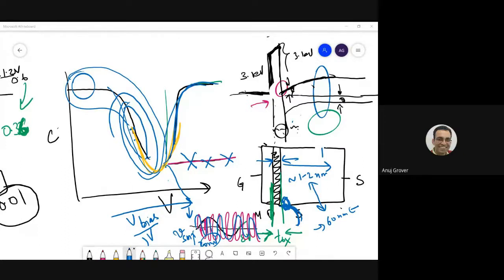Yes. I had mentioned once that we would use high K metal gate dielectrics and we could pin the VT to some level. I could modulate the VT of the device. What do you mean by modulating the VT? You will modulate the band bending.